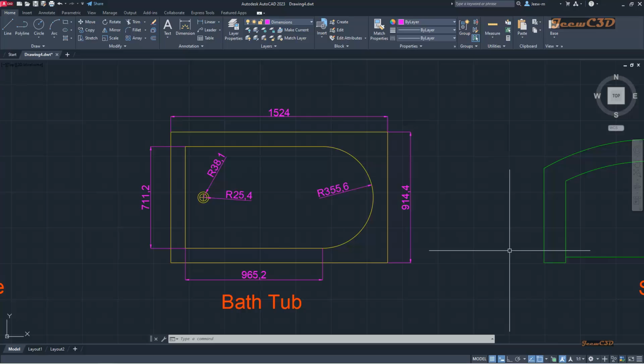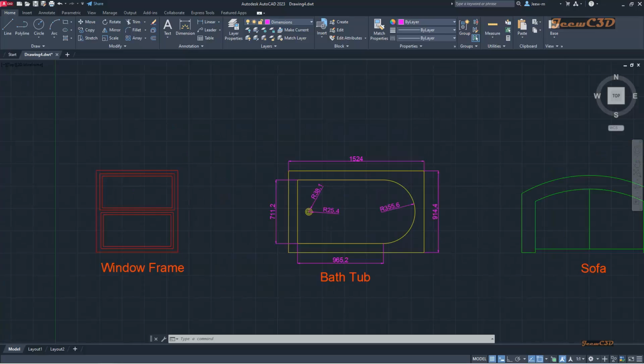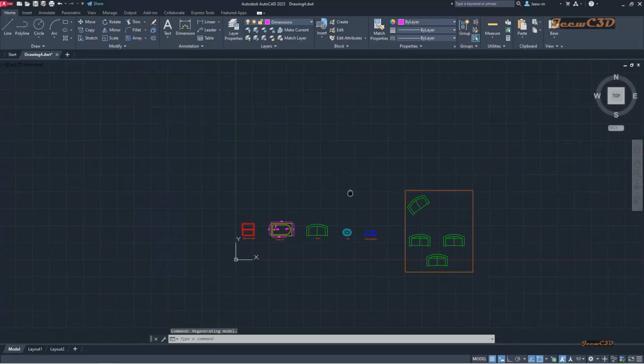Finally, we are going to talk about drawing templates. So here on my screen, we have created some objects, and we have also created a block. So let us say we need these layers, and sometimes we need these blocks time and time again on various occasions in our drafting. Instead of creating this every time, there is an option in AutoCAD to save these layers and blocks in a separate drawing type called drawing templates.